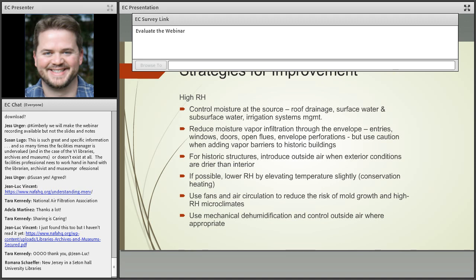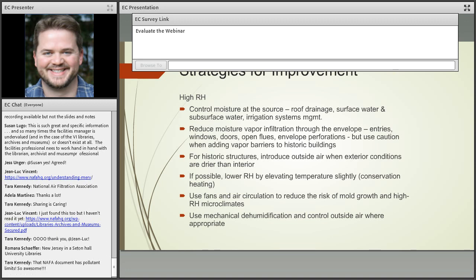That's the easiest, and I realize that isn't necessarily easy, but sometimes that's the easiest stance that you can take. You can get into looking to see whether or not there's any additional capacity in your cooling coil or in whatever system you're using for dehumidification, but chances are pretty likely that it may be maxing out the capacity for dehumidification already. So it's really about minimizing the incoming load and minimizing outside air. And finally, the other thing just to keep in mind in those scenarios,